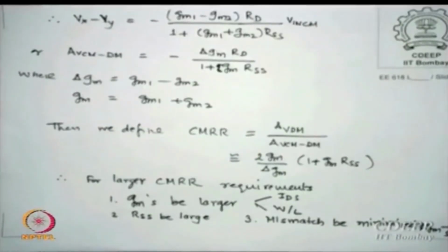Same way, we will never say power dissipation should be so much; we say it should not be more than so much, or the slew rate should be at least this much, gain should be greater than so much. These are the upper and lower bars we must decide, because then only design is possible.